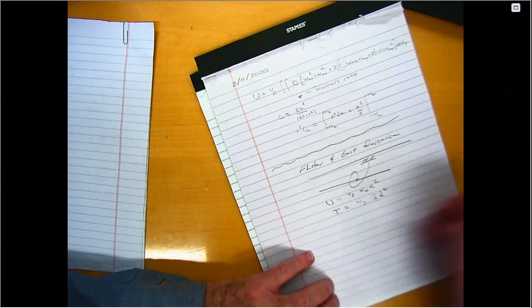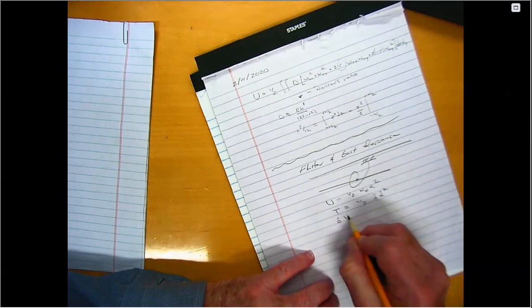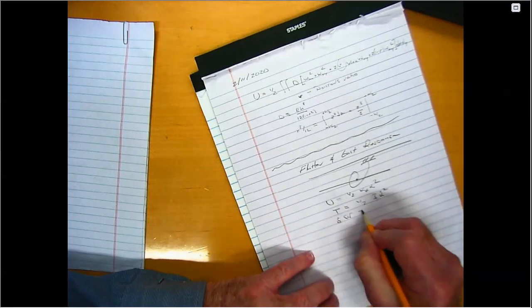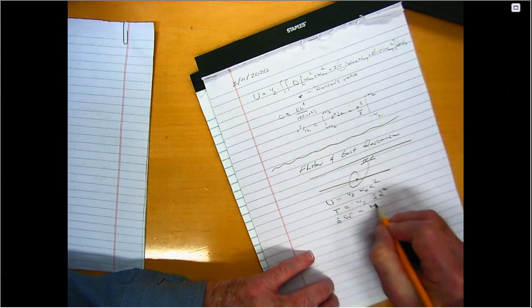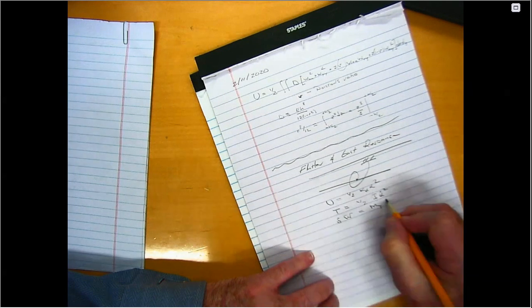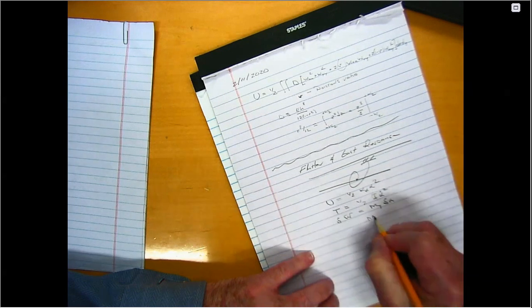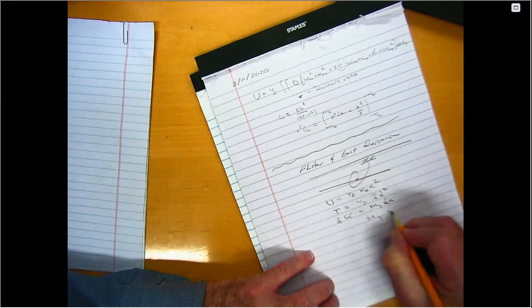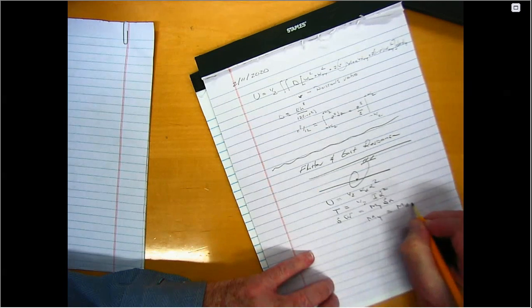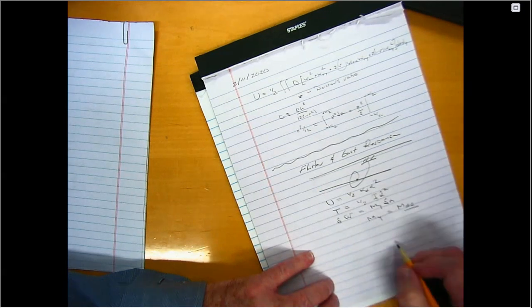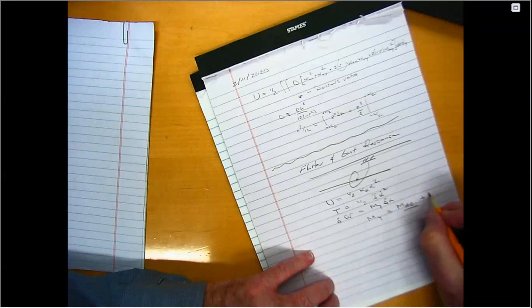And then there's virtual work, of course, which with this model is M sub y times delta alpha. And M sub y, as before, is the moment about the aerodynamic center, which by definition doesn't depend on alpha, plus the lift times e.